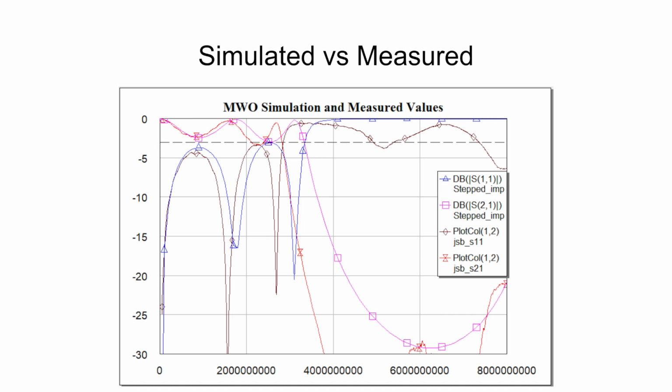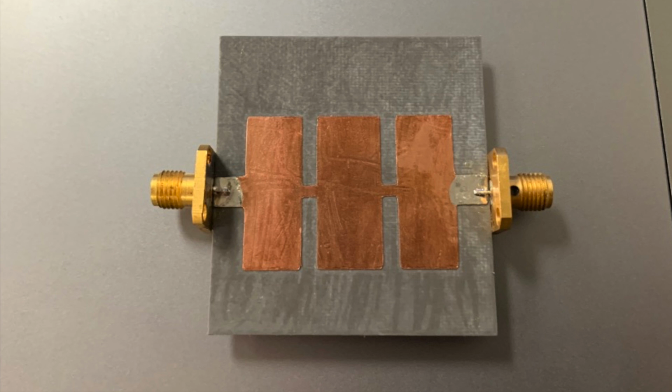We noticed that the trend of the plots is similar, but the cutoff frequency of the fabricated filter came out lower, at around 2.4 GHz. Although our filter provided a decent 3 dB ripple in the passband and a steep attenuation, it did not perform how we tried to design it to be. We noticed that the copper wasn't cleanly cut at the edges, especially when the width became small. Imperfections from the fabrication process may have caused the filter to not perform like how we wanted it to.